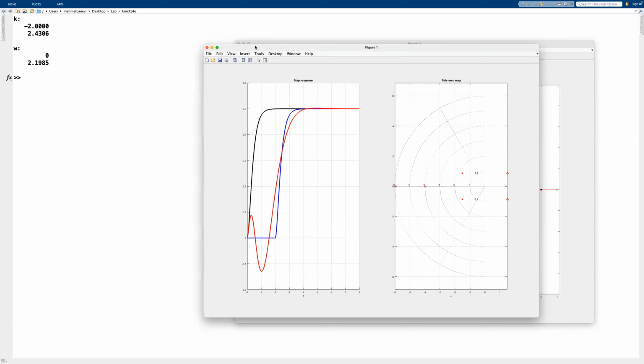Because it's an approximation, and we've seen, or we are still seeing, that we did use the first order one, and even the second order one was not capturing the behavior of the system. So is it reliable? And of course it's not. So when you use the Padé approximation and you come up with an interval, you cannot claim that the system will be stable in that interval.